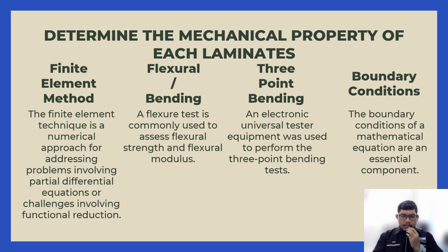First is finite element method. The finite element technique is a numerical approach for addressing problems involving partial differential equations or challenges involving functional minimization. A domain of interest is divided into a collection of finite elements. Approximation functions are expressed in terms of node points of a desired property field, and a finite element problem with a certain order value is created from the continuous physical issue. A sequence of linear algebraic equations should be solved to solve a linear problem.